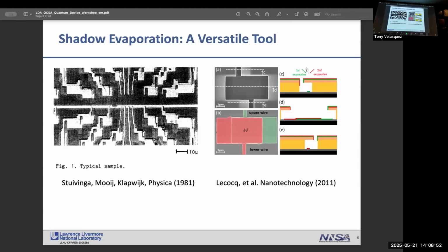So in the SEM, you can see maybe a 5 nanometer length scale, best case scenario. The junctions are about 2 nanometers thickness. If you section your device and have the best SEM, perhaps you can see the junction. But if you just put your device in the SEM, you will not.